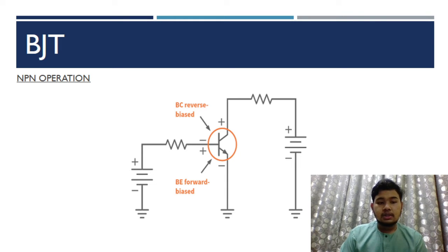The P-type region is just lightly doped, which means it doesn't have many holes in it. In this case, only a small percentage of free electrons from the emitter region can recombine with the holes in the base region. The small number of free electrons that recombine with the holes in the base region move through the base region as valence electrons.